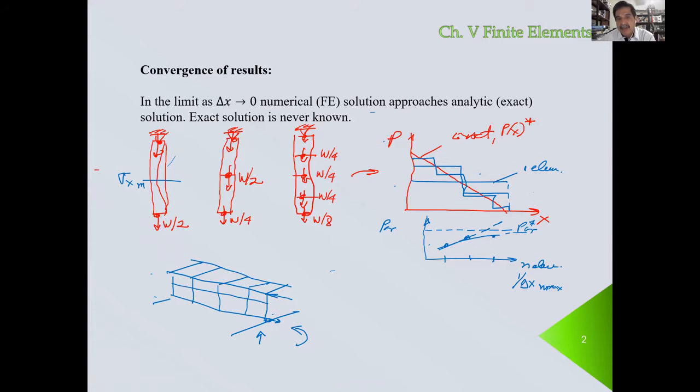So some classification societies, for example, specify the maximum dimension here. In some cases they say, for example, that the ratio between this dimension and this height cannot be larger than a certain value. Or they can tell you directly how much this maximum dimension could be. So these are 2 ways that you can check your convergence.